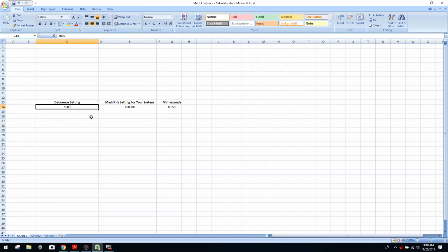And like I said, starting with 1,000 is really good. If you're at 100,000 hertz, it's a good setting to start with as a buffer. See how the system performs. If everything is right and your switches seem right, you've just added a nice little buffer to your system. If you are experiencing false e-stops and whatnot, start working the number up. Use logic. Don't go more than 5 times the debounce setting typically.